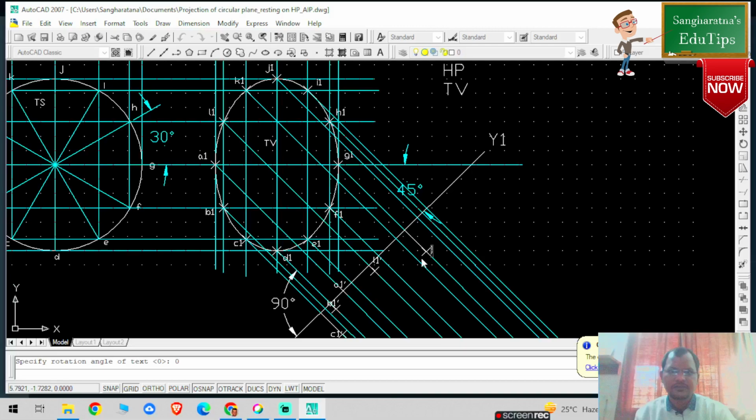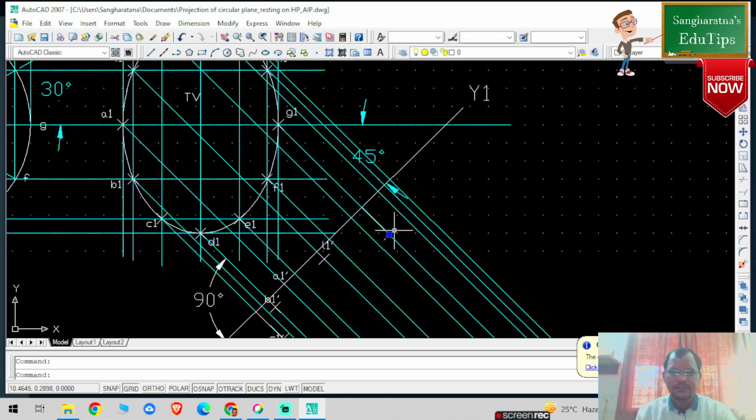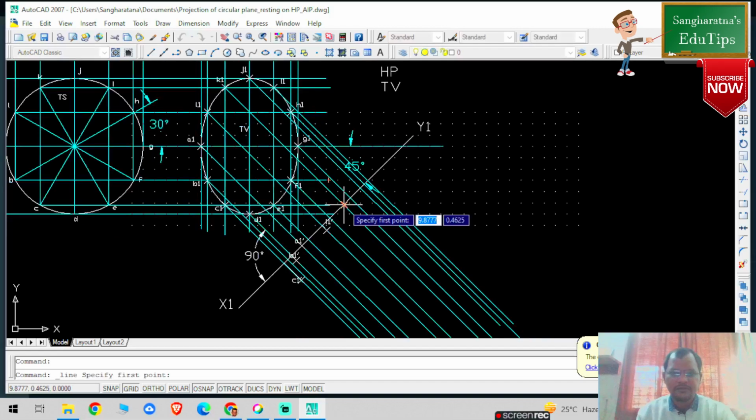You need to check, dear students. Press escape. Select this particular point, delete it. Select this particular line, delete it, because I have not marked on the K1 projection line. I have marked on the some other one. So this is my K1 projection line. So this is 0.5303. Press tab, 45-degree rotation angle. Now press escape. So now this is my